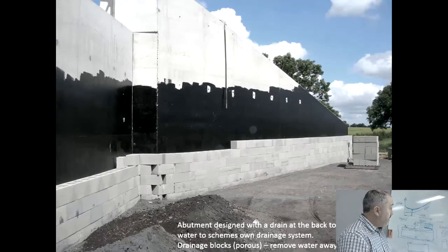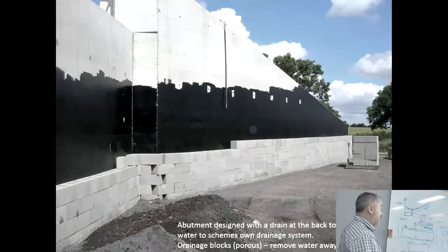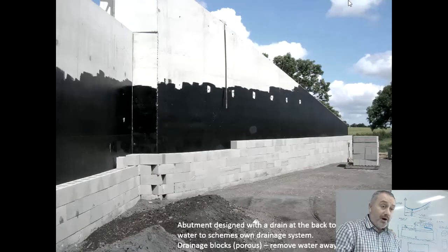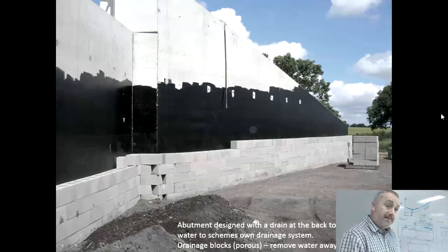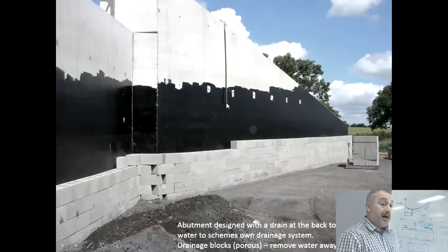This is the embankment side of the retaining wall, and what we have here is, as I mentioned, the pressure from the ground material and the water. Quite often you have some form of drain at the back, so all of the ground material would be containing water, and that comes down the inside through these hollow blocks, and there'll be a drain that just takes the water away.